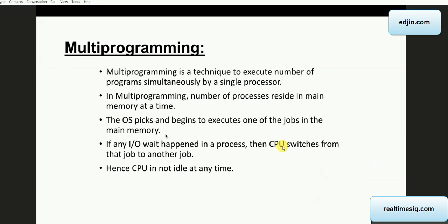The timers could be hardware timers, or they could be software timers also. When I say software timers, it is not like some program is executing continuously to interrupt the processor. The processor itself maintains a timer register. Timer registers are part of the special purpose registers where you program the time. Let's say I want a 10 millisecond time interrupt.